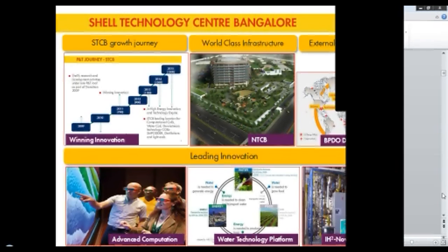I was wondering if using wastewater to generate electricity via turbines is a good way of improving the water efficiency. Well, this is certainly a very attractive method. You have to treat the water anaerobically, so the bacteria convert the organics into methane gas, which can be sent to the turbines to make electricity. However, anaerobic processes cannot operate on pure hydrocarbons. So they can only operate on water that contains compounds like, for instance, methanol, that can be split into methane and CO2. And if that's the case, then indeed it's a very good technology. And we apply this, as a matter of fact, in one of our chemical plants in the Netherlands, Moerdijk.